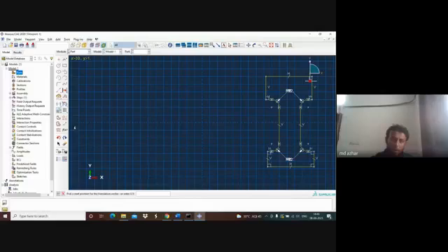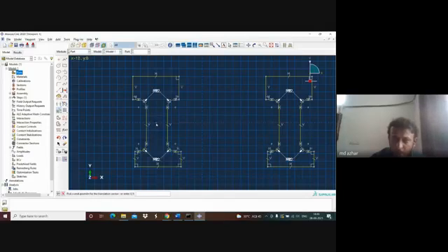Similarly, you can create a copy of it. If you see this, you can create the copy of it. Okay, select the entity to be copied. Suppose you have multiple entities in your software, then you'll do done. Then you'll have the start position here, and then you can have the end position here. So you can see that your two samples are created. Two tensile samples have been created. So this is what I'm telling you about the interface and everything.